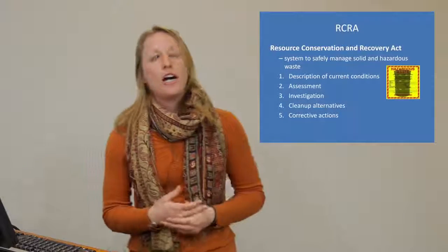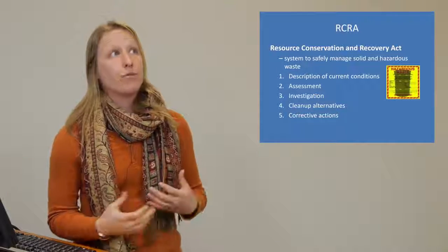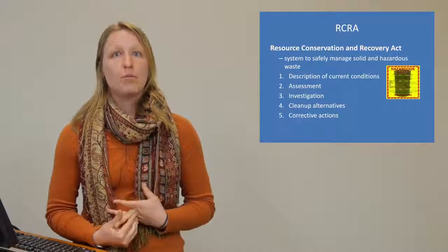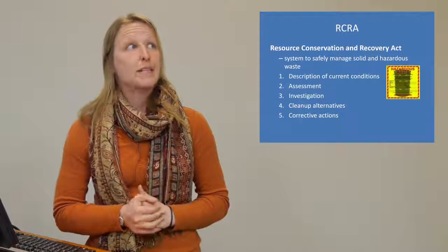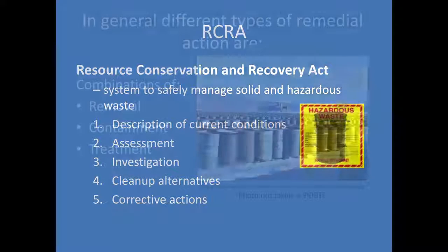Cleanup decisions are made based on RCRA, or the Resource Conservation and Recovery Act, through consent decrees with the state and federal government. What this includes is an assessment of the site and a description of current conditions, and from that, an investigation to figure out the removal, containment, and treatment options in terms of our cleanup alternatives. And groundwater modeling has a central role in this at Ports.